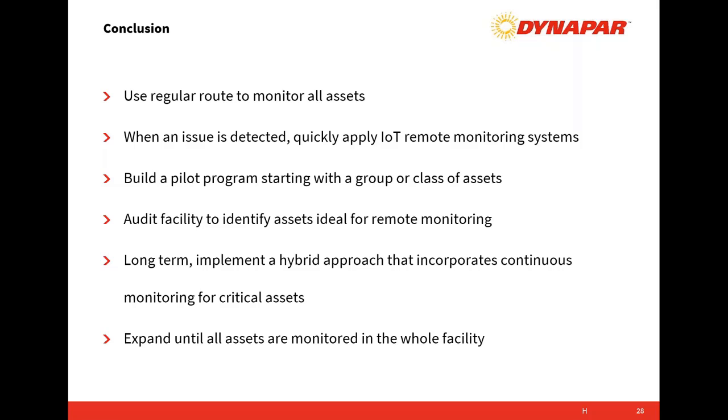Great. The next question that came in is, how is the hub powered? Good question. So we have several different modes. One, the standard starter kit comes with a 12-volt supply that's class 2 rated and can plug into any regular AC power outlet. The unit can also be directly powered off of machine power that may be available. So any power supply, 7 volts to 40 volts, can be tapped in to power it.